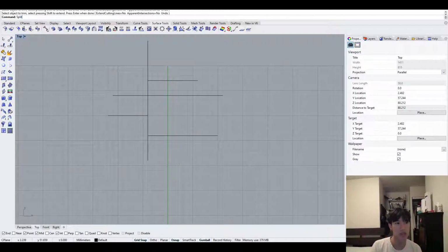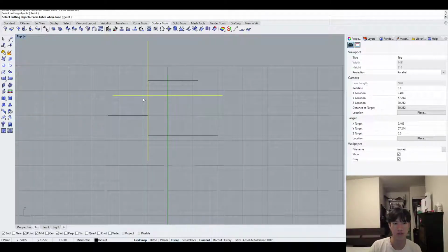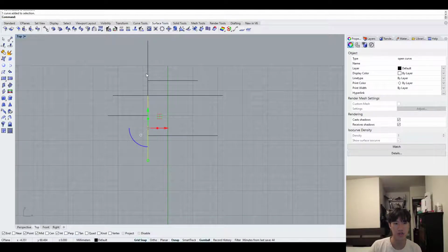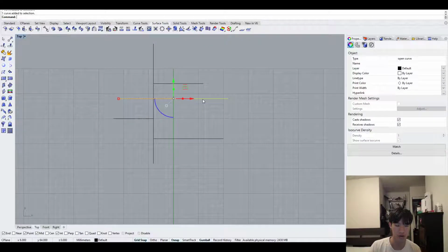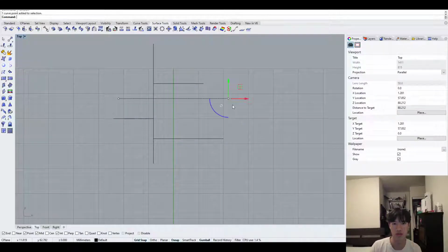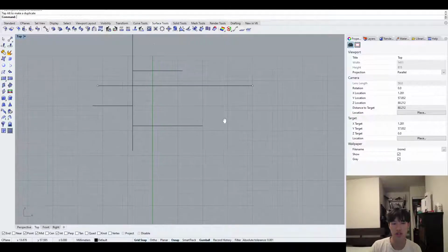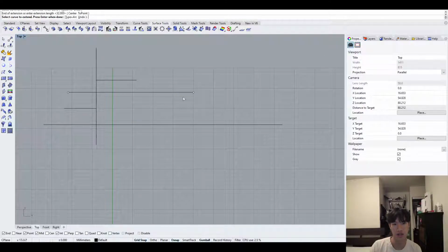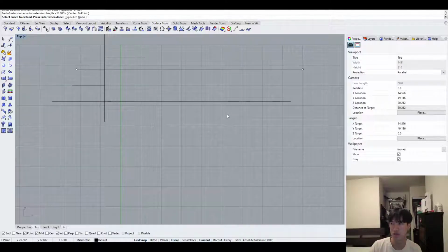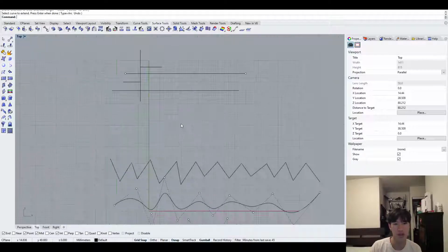Another one is split. So let's say I choose which curve to split, and then I choose which object to split it with. So you can pick another curve, and then this curve, see here, gets split into 2 pieces, right? Oh yeah, F10 and F11 also work for this, like points on and points off. So you can turn on points on straight lines and extend those. Another way is to do extend, which allows you to literally extend the curve by clicking on it. That's pretty self-explanatory.